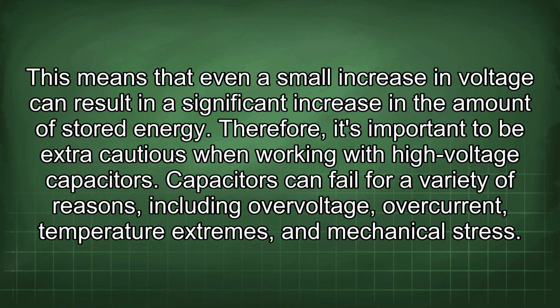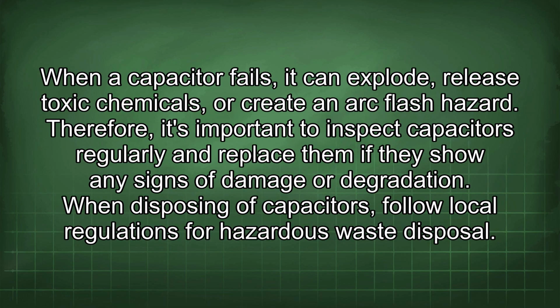Capacitors can fail for a variety of reasons, including overvoltage, overcurrent, temperature extremes, and mechanical stress. When a capacitor fails, it can explode, release toxic chemicals, or create an arc flash hazard. Therefore, it's important to inspect capacitors regularly and replace them if they show any signs of damage or degradation.